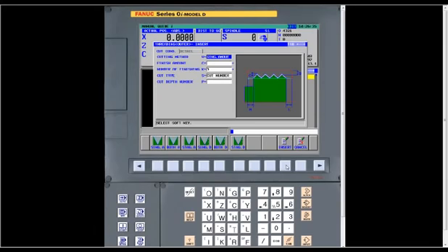But you've got six different ways of feeding into it. For the finish amount, you could leave a particular amount of finish stock or a particular number of finishing passes. And then also you can have cut type. You can have number of passes or depth of cut. Those are your 2 choices. I'm an old engine lathe guy, so I'm used to cut number. I've got in my head how many passes I want to take, so I always use that. But some people always think in depth of cut. That's all right, too. It'll work both ways.